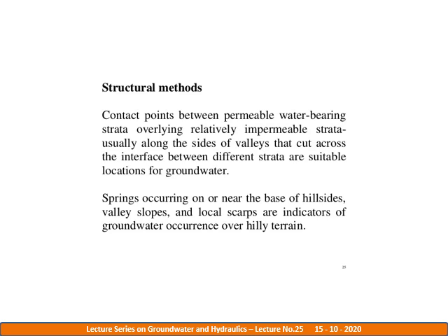In the second phase, field investigation will be prepared based on some surveys, inventory of existing wells, geophysical survey, test drilling, pumping test and other investigations like net thickness of the basin aquifers. In the third phase, additional data will be required like inventory of existing wells, geophysical survey, pumping test and other investigation.